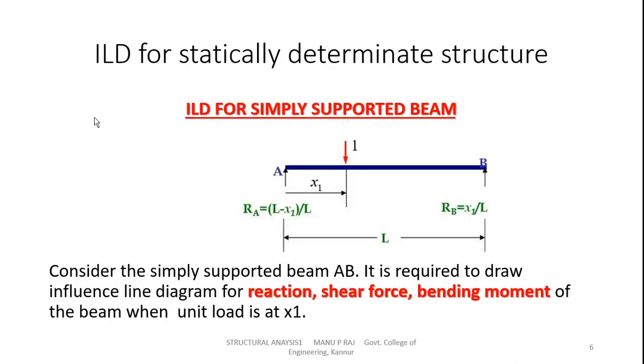Now, ILD for statically determinate structures. Consider a simply supported beam and there is a load of 1 kilonewton acting at a distance of x1 from the support A. We are going to derive the influence line diagram of reaction, shear force, and bending moment for this beam.